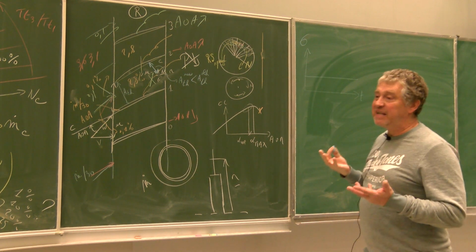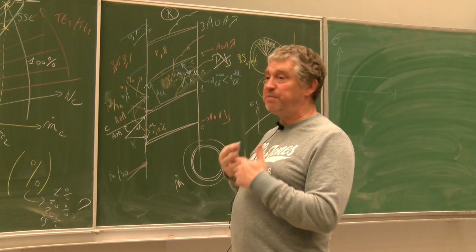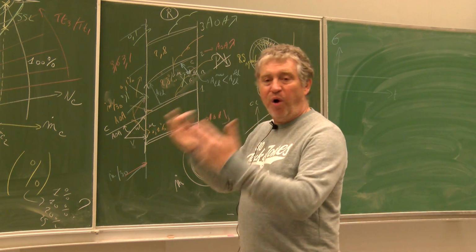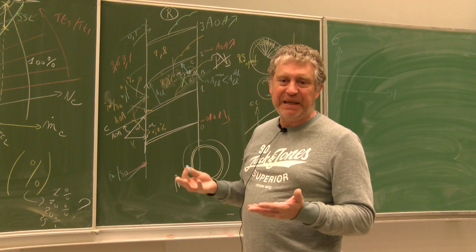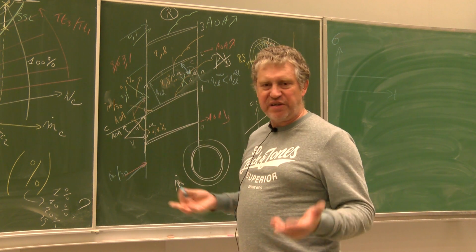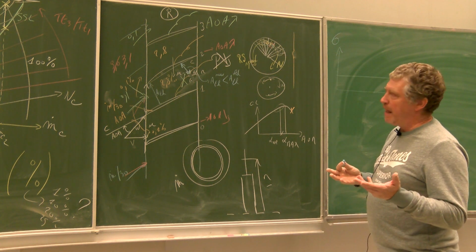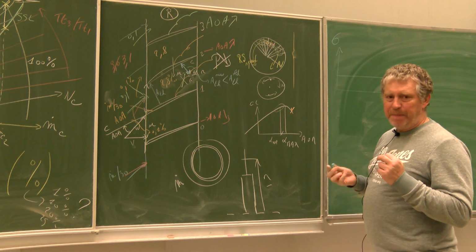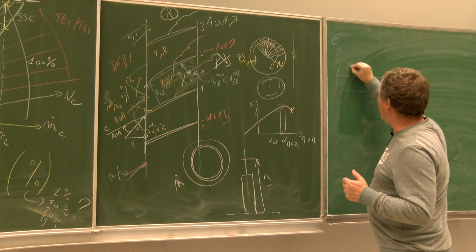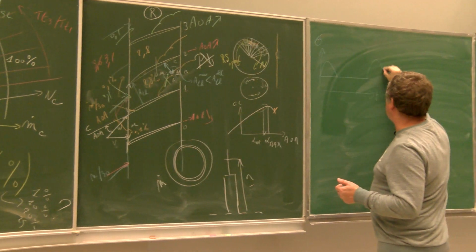In a steady state condition, the blade is always rotating at the same rotational speed, always seeing the same m dot, always seeing the same speed of the flow, always seeing the same delta P over the suction side, pressure side, etc., always the same rho. So you see a constant load in steady state. And due to this perturbation, you will have something like this. Hop, and then it disappears, and then comes back.